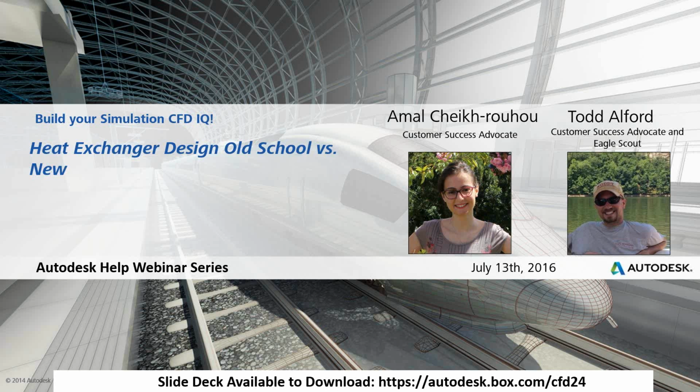If I need to be using the SST turbulence models, I will, but when it's not going to give me something massive and I know I'm going to have to go through 60 clicks in meshing just to get an appropriate mesh, if I can get in there with K epsilon and get some reasonable results easier, and I'm paying a few percent, not a big deal.